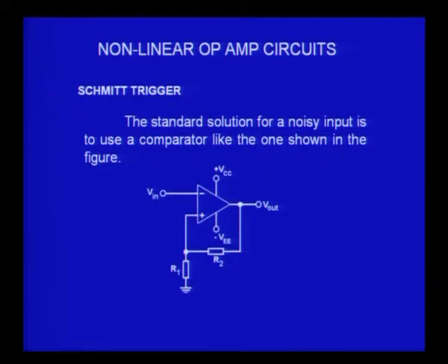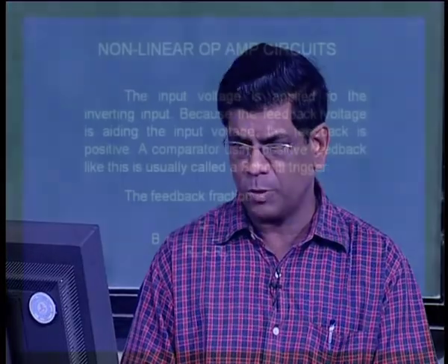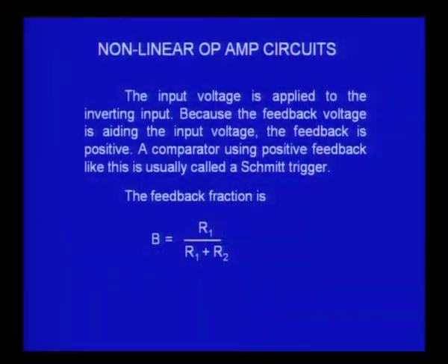So, from plus or minus 150 microvolts, we have now expanded the variation to plus or minus 1.2 volts, which is a very large difference. This 1.2 volts cannot be generated by any noise voltage in the normal course, and therefore we do not have to worry that the output switches state because of the input noise. So, this is also called by another name, Schmitt trigger.